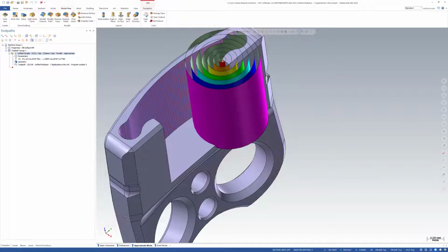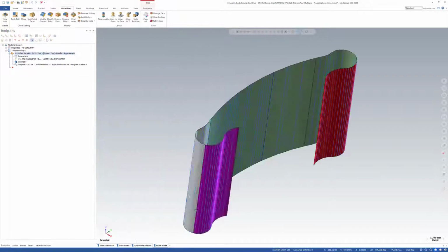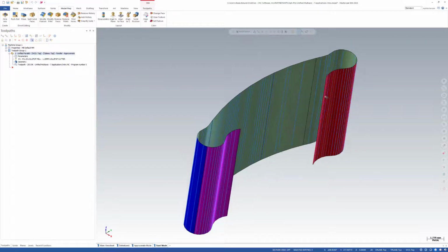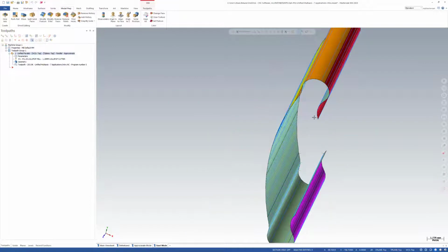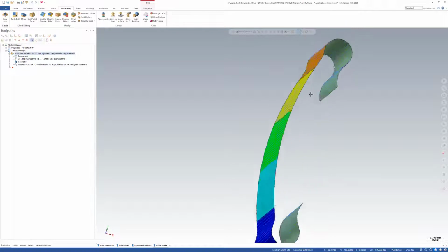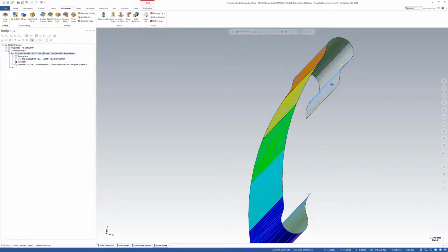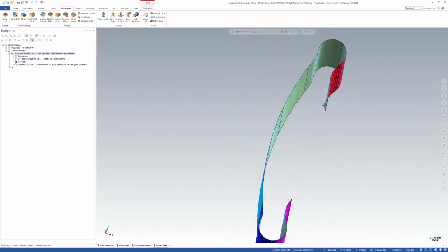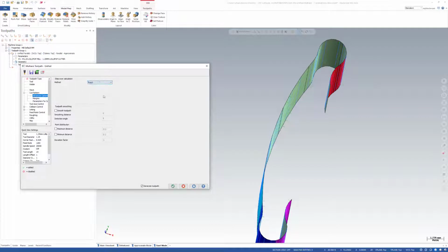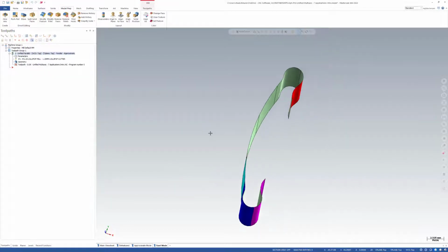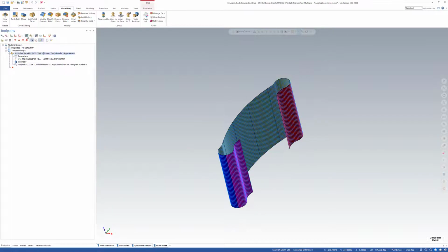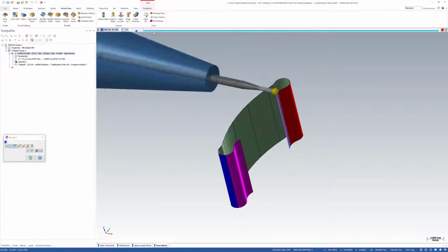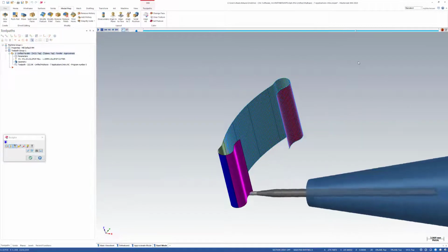So simply by changing this over to exact mode, it will work differently, where it propagates by measuring along the length of a surface. Exact mode will not generate stepovers through open air. So if I change this over to exact mode, we see that same toolpath becomes much more useful.